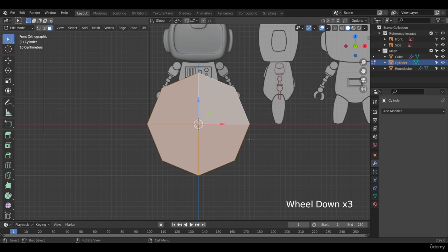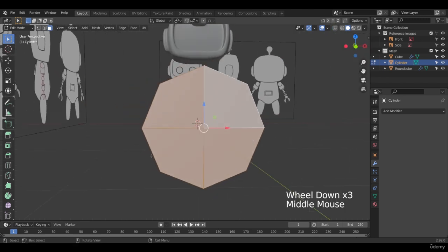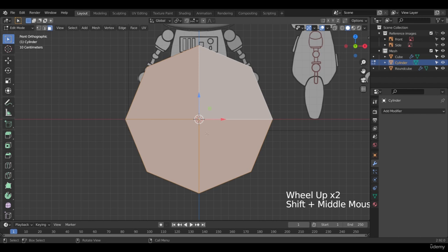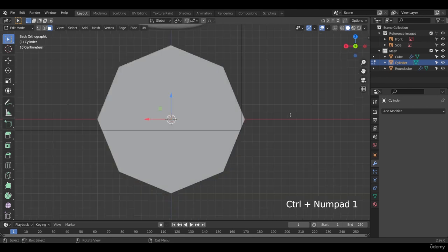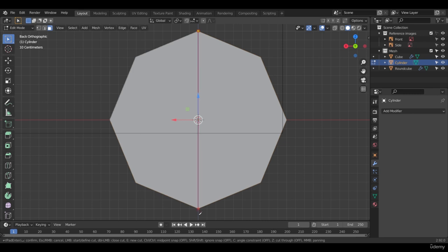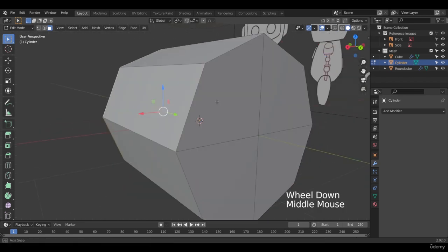We press enter, and now look, it's the same shape that we had before, but we have faces with only 4 vertices, which is what we want. We're gonna do the same on the other side. So we're gonna press Ctrl R, and we're gonna do exactly the same. We define it, enter, okay, enter. There we have it.